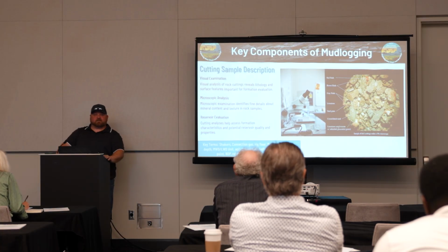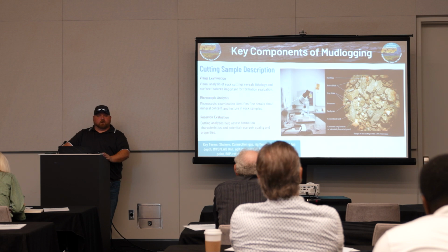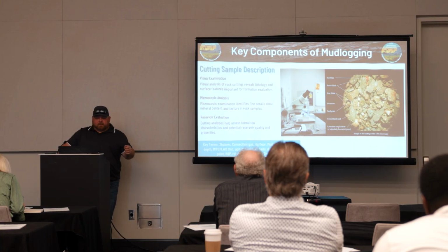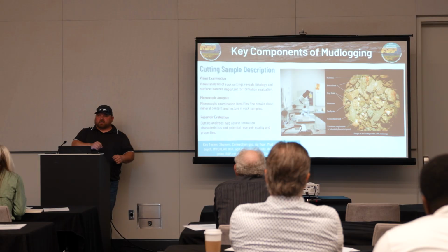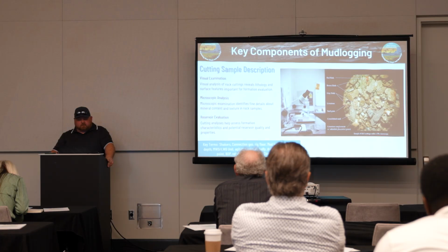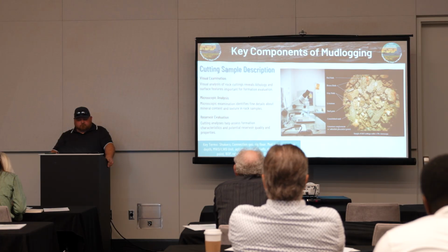Limestone will stain bright red almost immediately. You can put some alizarin red on there and then splash a few drops of HCl on it, and it'll dilute it to where it'll actually react with the limestone better, the calcite in the limestone.